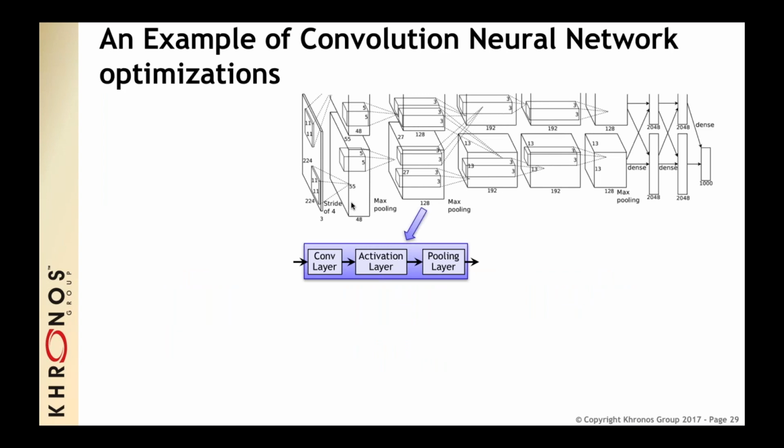Okay, so what we have in the OpenVX neural network extension, as I said, is a summary of things. We have int16, Q78, int8, and U8, as I talked about with the quantizations. Vendors can support more if they want. As I said, we need an algorithm for quantization for that. We also split it into two extensions: the full 16 and 8-bit support, and only the 8-bit support.